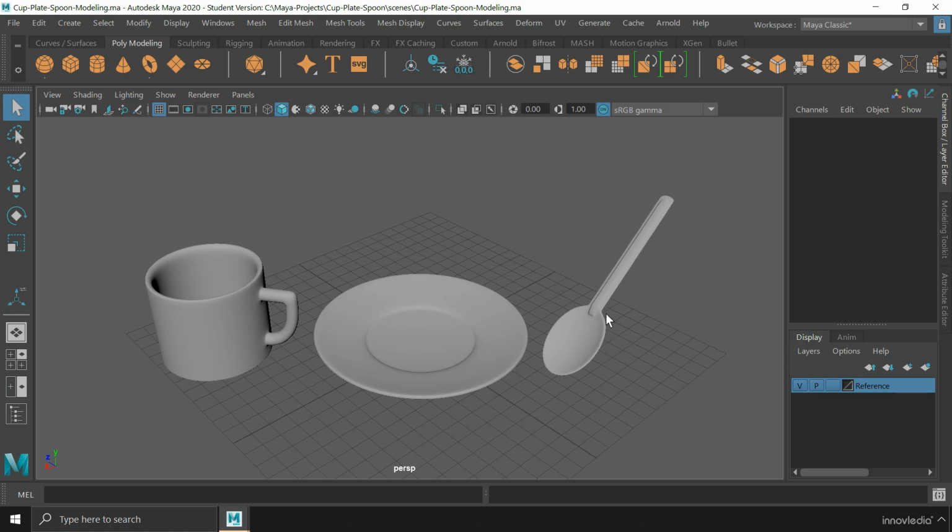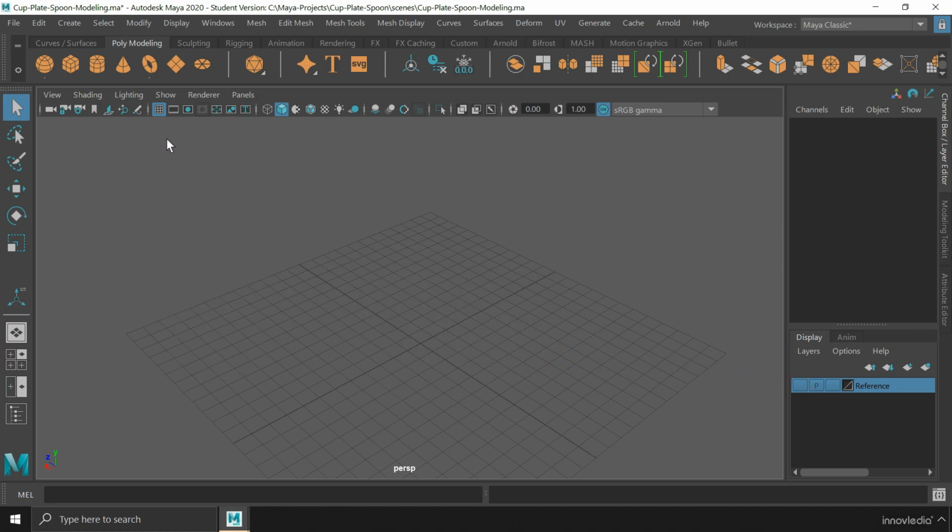Once you understand the profile or shape of the object, you can select the primitive object that should be best to begin with. And eventually, you would be able to transform that primitive object into whatever you are trying to create. As this cup is cylindrical in shape, I am going to start with a cylinder and keep modifying it until it becomes a cup. Alright? So, let me first hide these objects and then create a cylinder. It can be of any size as you create.